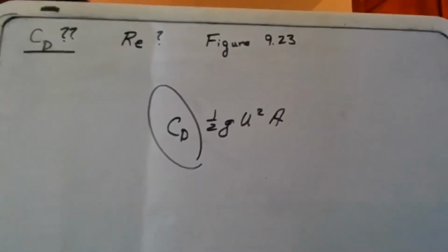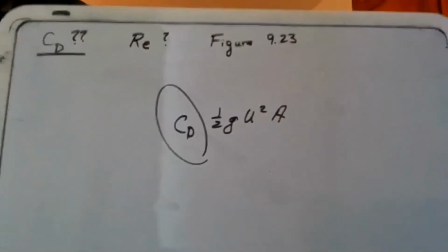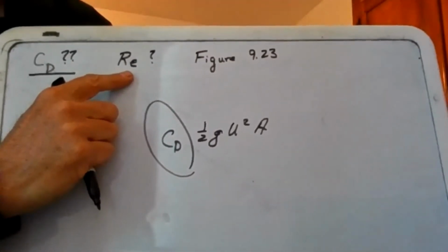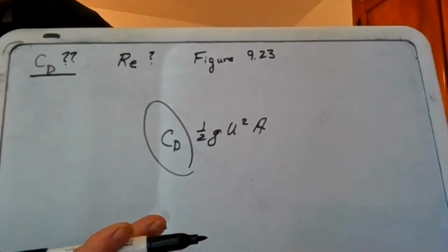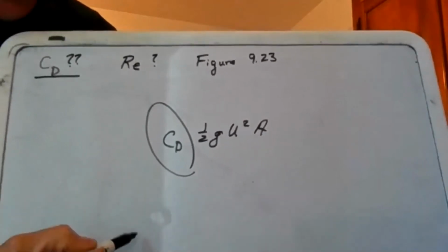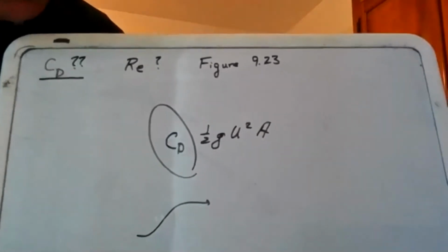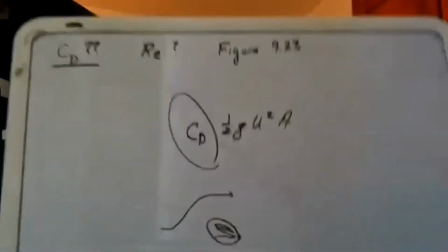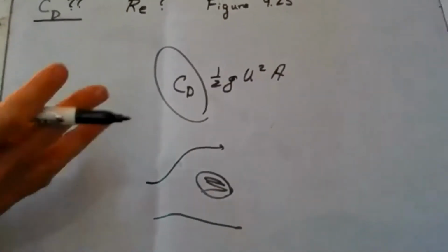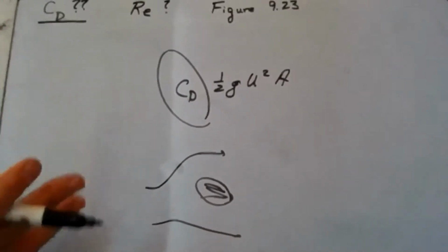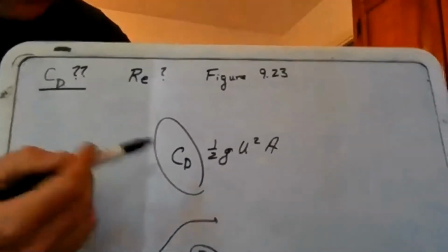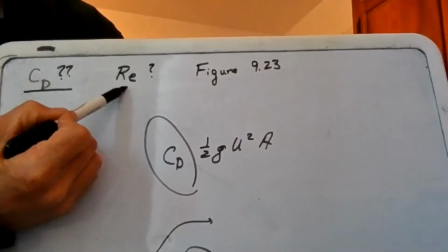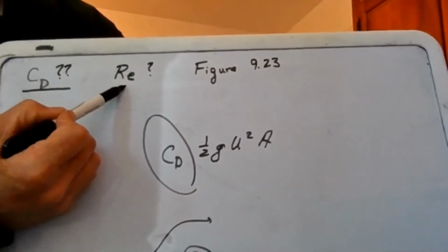And so what the convention that's come out there is, in some cases, we base the coefficient of drag on the Reynolds number. That might make some sense. The Reynolds number gives a sense of, hey, that flow around our object. How close is it to turbulent, or is it fully turbulent? And the nature of the flow, of course, hopefully makes some sense to you guys, would determine the nature of the drag. So we determine the Reynolds number, and you got to be careful about how the Reynolds number is calculated, and then go to some sort of chart.